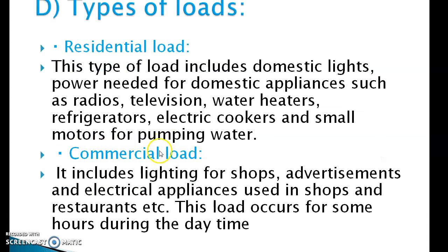Types of loads. First one is residential load. This type of load includes domestic lights, power needed for domestic appliances such as radios, television, water heater, refrigerator, electric cooker and small motors for pumping water. Commercial load. It includes lighting of shops, advertisements and electrical appliances used in shops and restaurants, etc. This load occurs for some hours during the daytime.